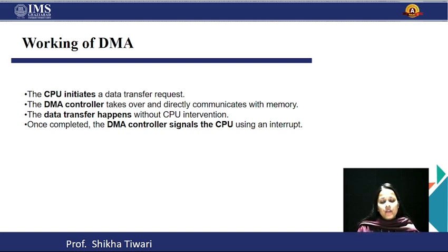But when the CPU initiates the DMA transfer, it relinquishes its control of the buses and provides control to the DMA controller. The DMA controller is the actual operator that performs the task of transferring data between input-output devices and the memory.